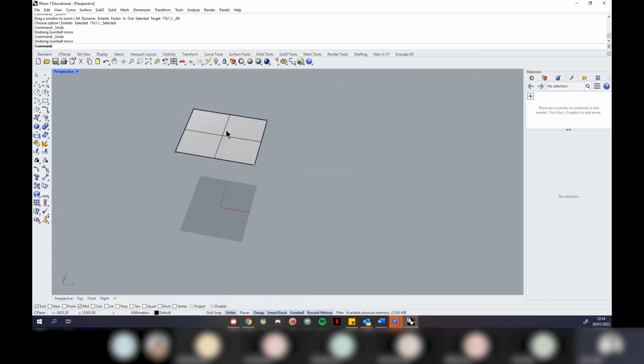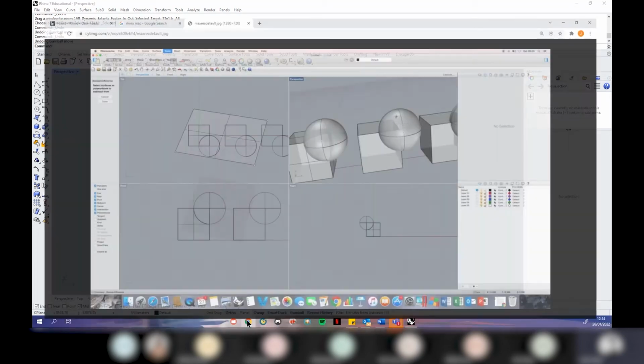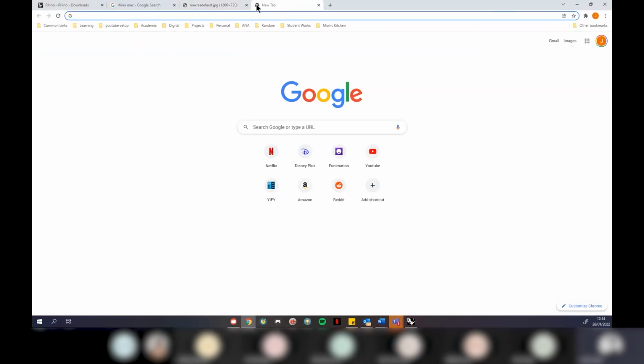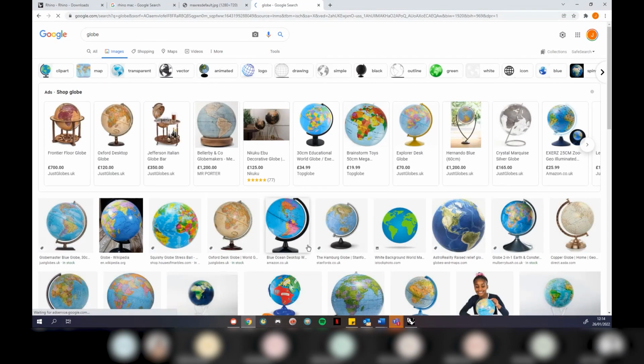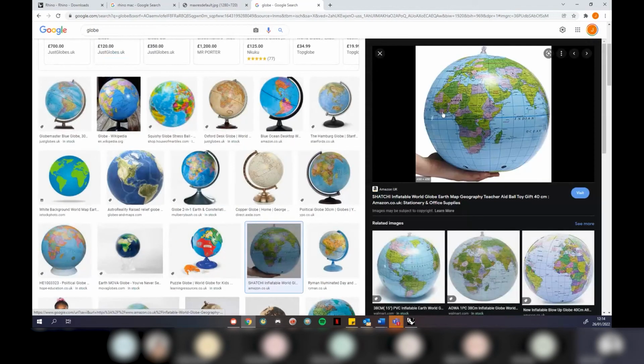Now, surfaces or 3D objects have their own coordinate system. They could be moved around on the X, Y, and Z axis in 3D space, but the object itself has its own coordinates. And a good way to think about this is if you think of a globe. Think of the grid that's on a globe. Essentially, this is what we call U and V directions. So it's its own coordinates. V usually stands for vertical. I can never remember what the U stands for.